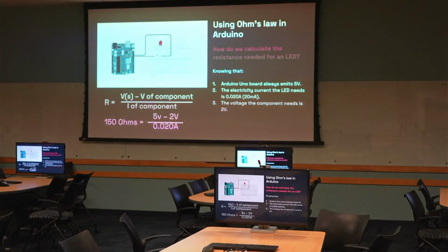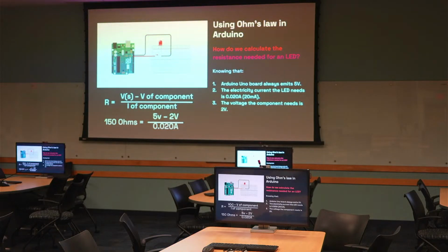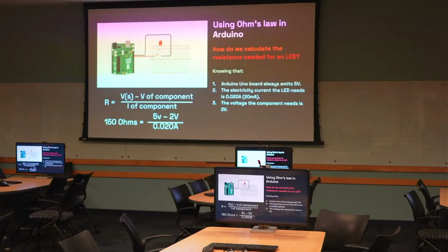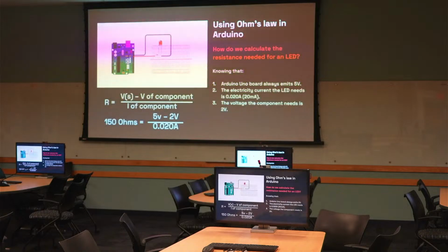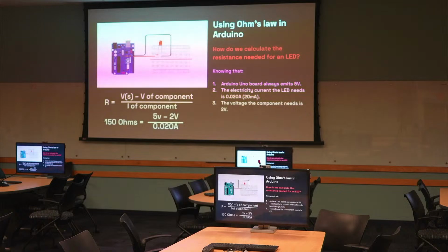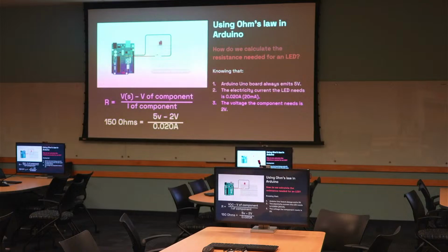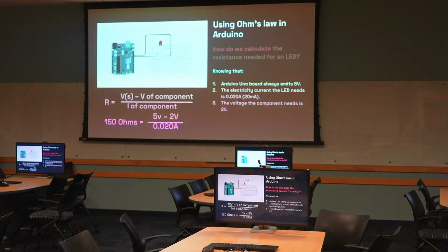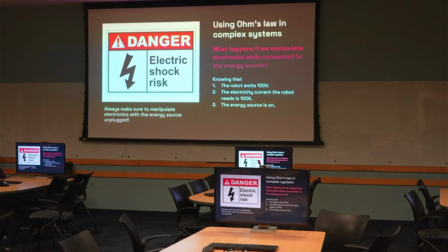So you need to start with that formula, because sometimes for LEDs you can just Google it and it will probably say 220 because it's widely used. But for example, when you are researching new components or working with electronics that are not very documented, you need to follow the formula. That's why it's a good practice to get started with the exercise of calculating everything. And make sure that you find the next resistance above that calculation. Always. Good question.